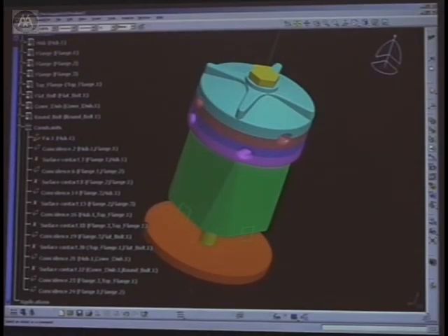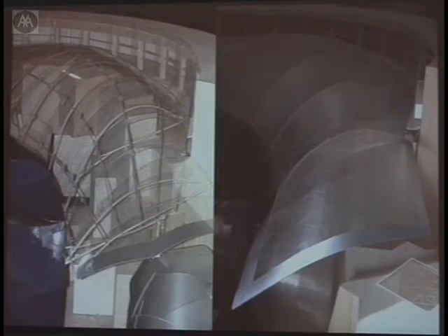You can do the same thing for the node joints that you did, for example, with those MIT panels. In this case, you have butt joints where you either have a weld, or diagonal tension cables that brace each one of these panels, and each one of these is going to be individually machined. So to detail all of these 8,000 different nodes would take an inane amount of time. You're not using a ball joint, a kind of Mero joint, because there's a lot of torsion in there, so we need a welded butt joint, mainly because this is a free-form surface and not a structural surface. Or rather, it does perform structurally, but does have to take up a lot of torsion between these members. So then the script basically runs through and can place each one of these in detail, all 8,000 of them for you. And so this is the result.